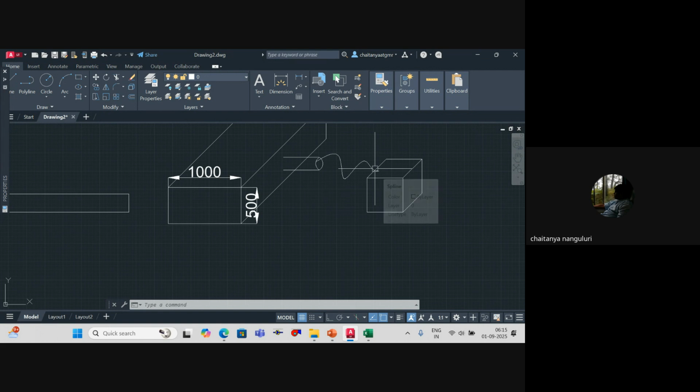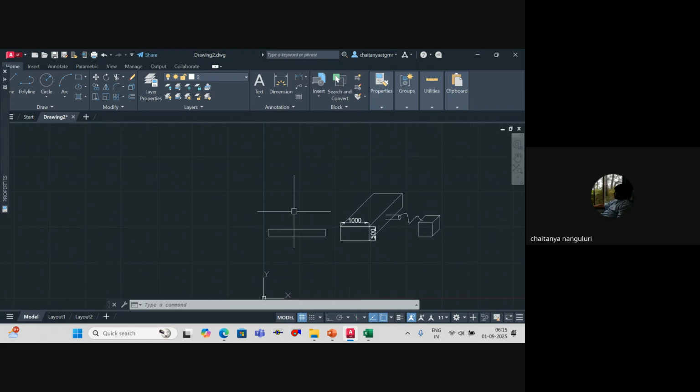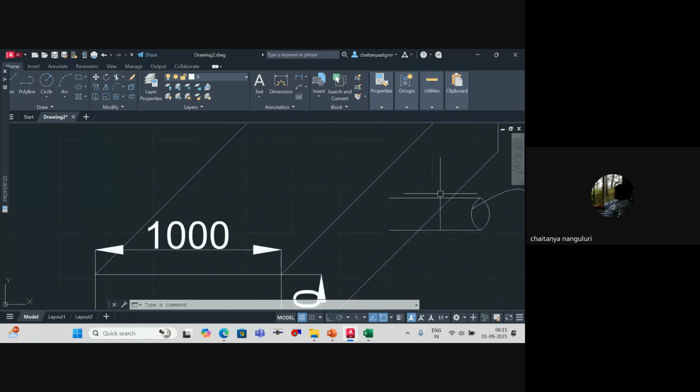So you have that flexibility, that fluidity in the design. That's the reason you basically use your flexible duct. Whenever we do it, from the main duct, you use a flexible duct to connect. In the olden days we used to go for collars, but now instead of collars we always go for these flexible ducts. Am I clear? And we provide some kind of damper here so that we can even control the volume of air. We can control the air properly for that reason. Understood?